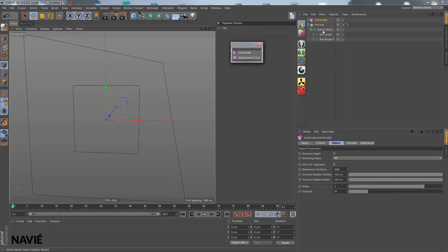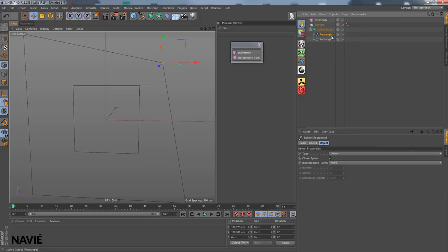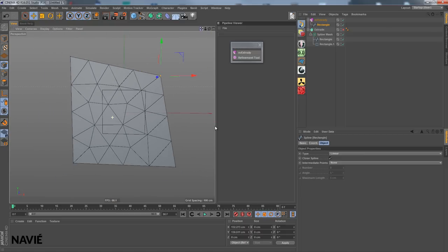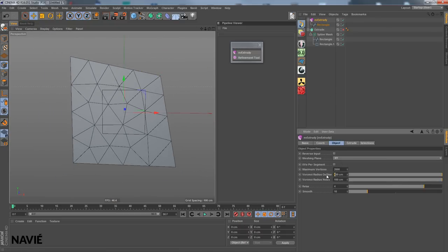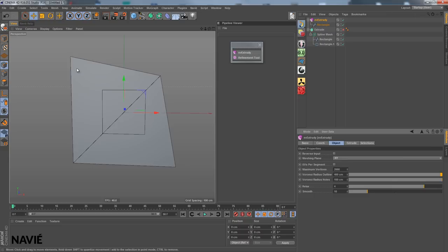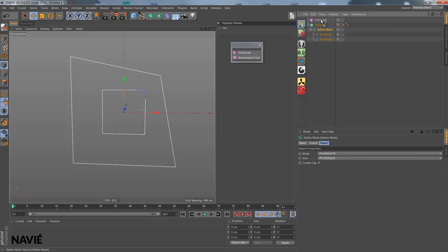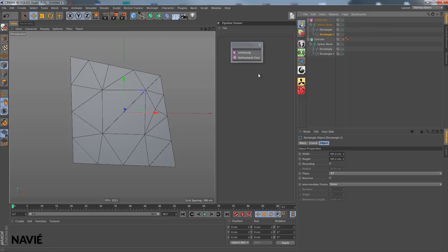And let's start, as we did before, with the original rectangle, so we see what happens there. And you can see also in this problematic case already that evenly distributed and evenly sized polygons are generated. And in the settings, changing the Voronoi radius outline to a high value will result in kind of the lowest triangulation possible. Well, let's just use the spline mask to get the actual result, and we see one difference here, that the rectangle shape is triangulated. I come to this later, but for now let's reverse our rectangle down here, and we see that we get